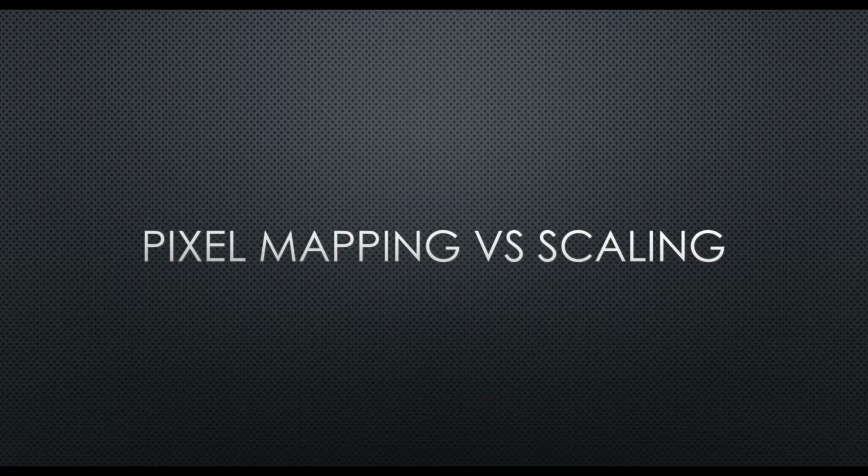Let me turn on a presentation here for you guys. So pixel mapping versus scaling, what are the main differences? Pixel mapping is basically mapping every pixel of your output signal, whether it be your computer, DVD player, or any sort of digital player supplying the signal, to the actual LED screen. They all have specified resolutions, such as 1920 by 1080 being HD resolution. In more than likely cases your LED screen is not going to be exactly 1920 by 1080 pixels, so you could utilize scaling. But there are a couple of different aspects to scaling, such as scaling out of proportion, in which case a circle in the image will look like an oval on the LED screen.